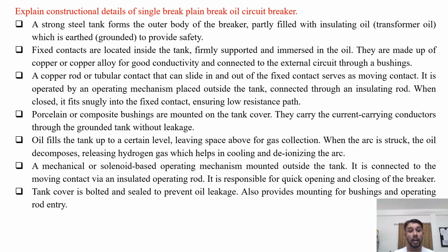A mechanical or solenoid based operating mechanism is mounted outside the tank. It is connected to the moving contact via an insulating operating rod. It is responsible for the quick opening and closing of the breaker. The tank cover is bolted and sealed to prevent oil leakage. It also provides mounting for bushings and operating rod entry. So this is the constructional detail of a single break, plain break oil circuit breaker.